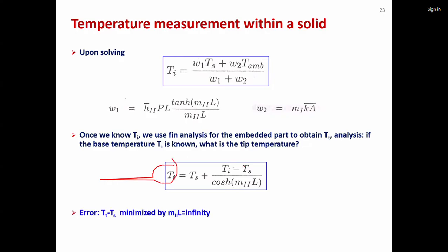So if you know the temperature of the tip, you can see here, you wanted to measure the temperature of the solid Ts. Now, what you are measuring is the temperature of the tip. So this difference is basically the error, and this error is nothing but this term.